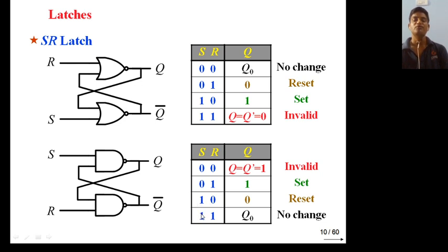You have to remember, you can apply the shortcut method only when any input is low. For 1 1, first consider the value of Q as 0, then next time as 1. With Q 0, you will get the same output, Q 0. With Q 1, you will get 1. So no change. This is all about your latch.